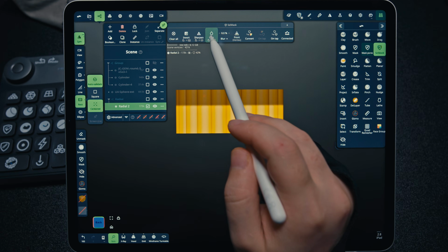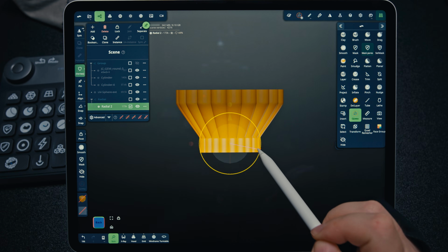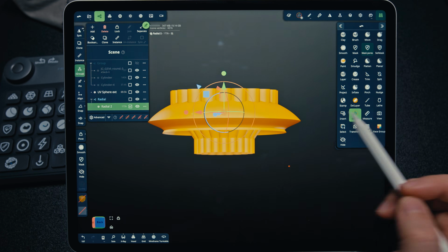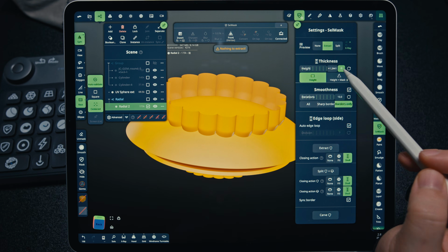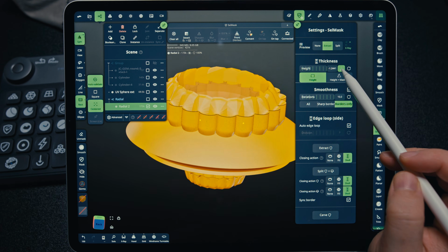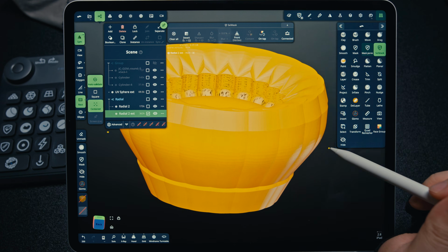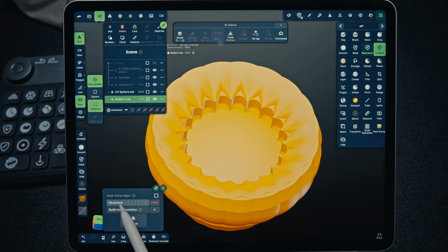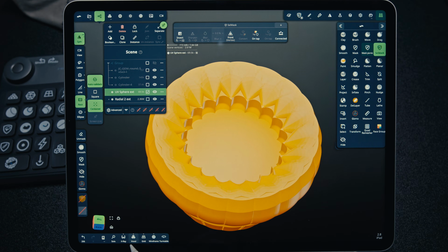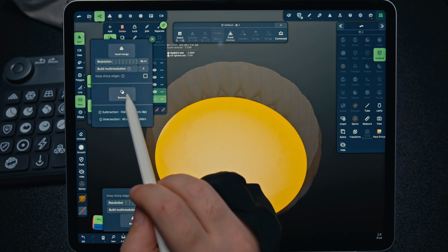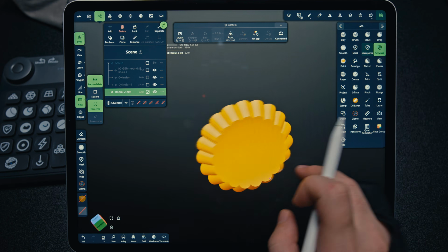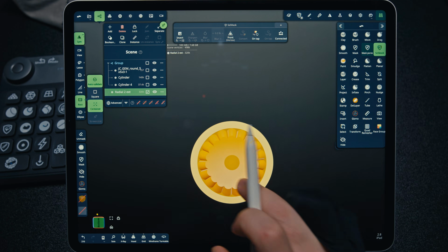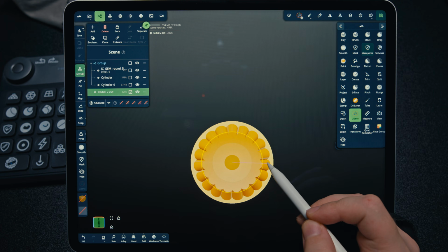And this part I will make cone-shaped like this. I'll mask it and give it some thickness. Next, it is absolutely necessary to do a voxel remesh of both of these parts. Now we boolean them and get this pie shape. But this pie now seems a bit too small to me, so I will increase its size.